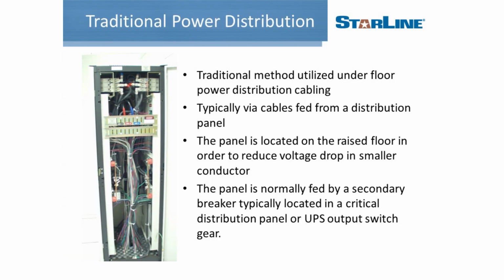I want to talk a little bit on the front end here about traditional power distribution. We've all seen these facilities before that embrace the traditional power distribution approaches, incorporating a raised floor with RPP units deployed throughout the facility. You can see there in that image on the screen, traditional back looking into the RPP with all the cables coming up from underneath the raised floor.